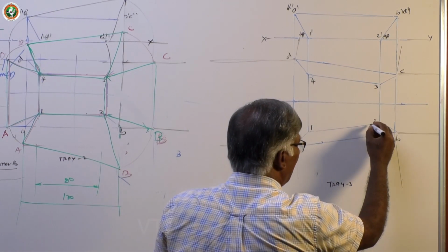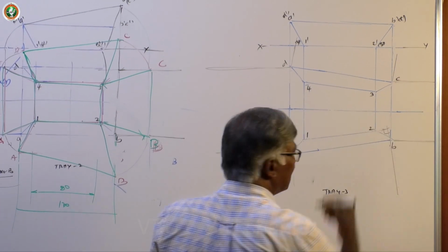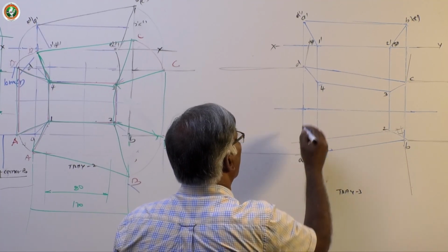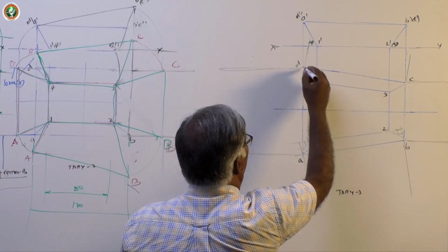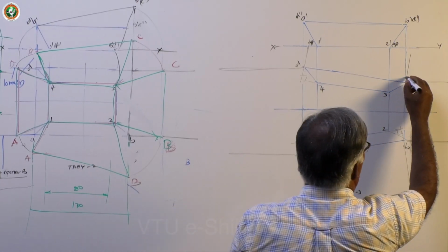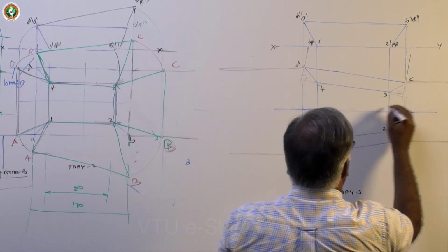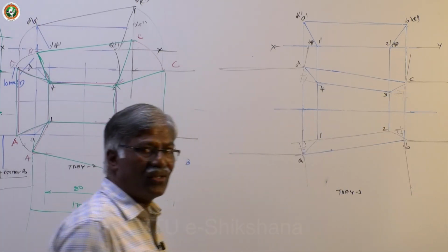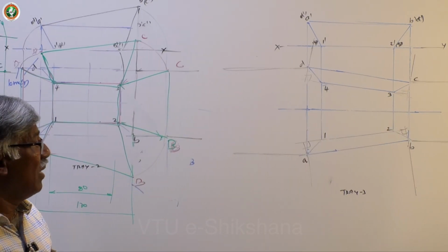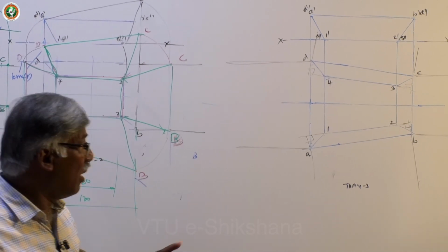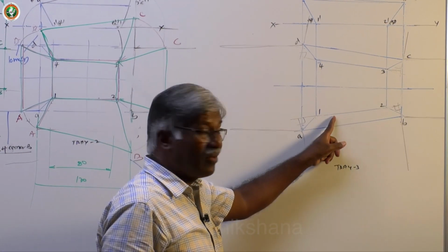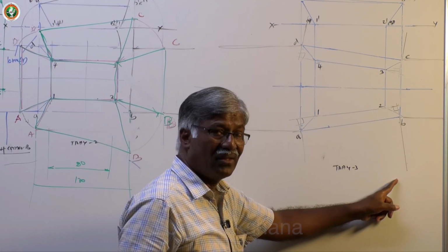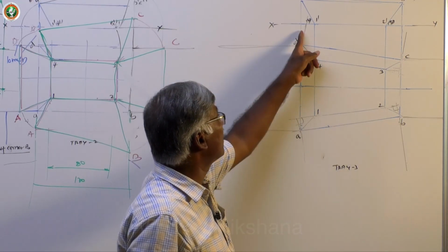So, if I continue this line and this line, this is an imaginary perpendicular. It must be clearly noted. This is perpendicular, and I am very particular about it. I project it purposefully to show you exactly what this line is. I continued 4, 3 and also projected this, and then showed the perpendicularity. So the paths traced by all the top corners are actually perpendicular to the base edges. Here 1, 2 is the base edge. These are the loci of B and A respectively. These are the loci of D and C respectively.